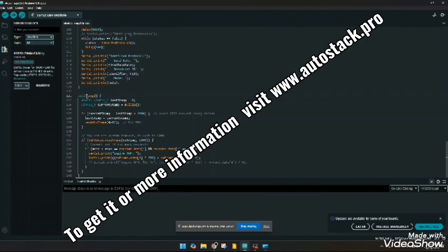And then there is the next function, loop, which loops over time to basically output the results iteratively. And in this function, we are basically sending this command for RPM again and again, and then receiving the response and printing it on the serial monitor.